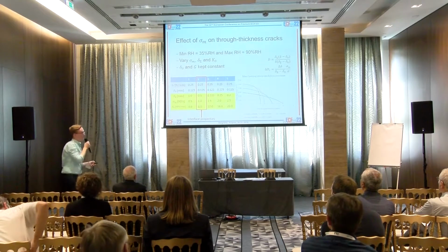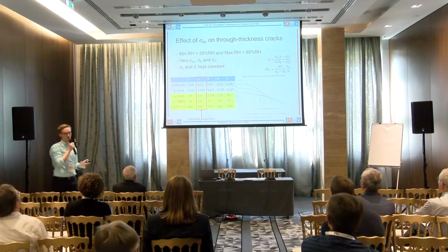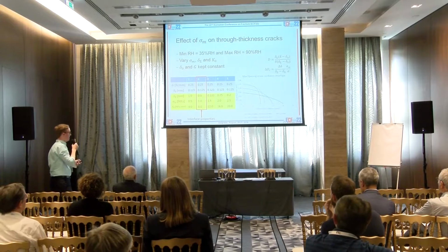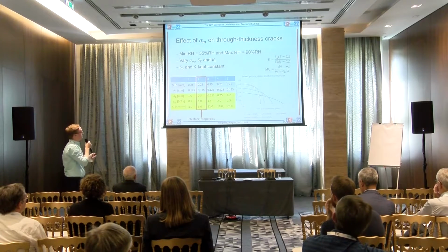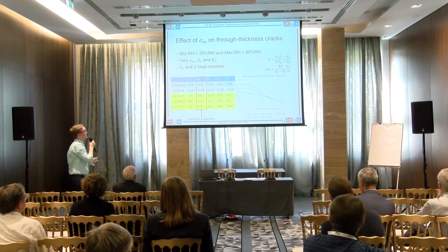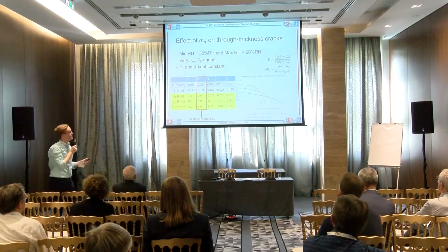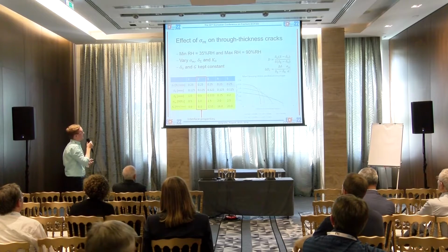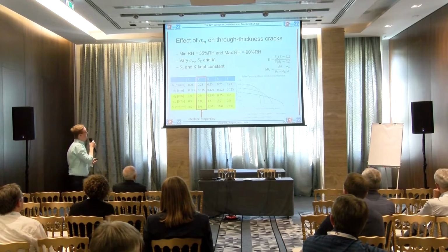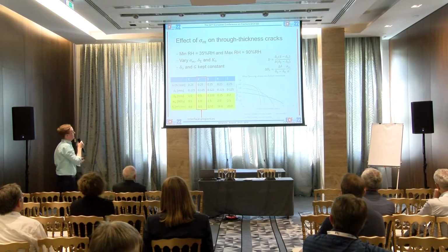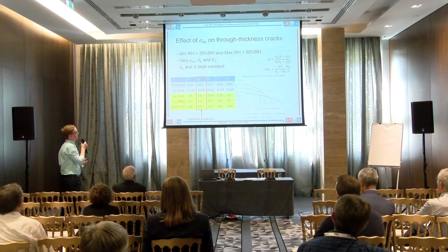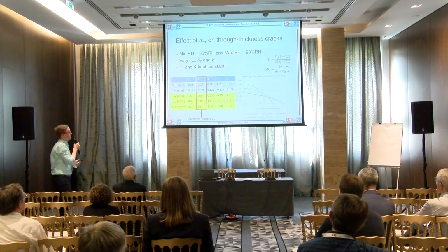So now we're going to do a parametric study on the through thickness cohesive parameters. The cycle that we've decided to use is the extreme case with 35% as the minimum and 90% as the maximum. Firstly, we're going to vary sigma m, delta sigma and k naught. We're going to keep delta naught and the fracture energy G as a constant.